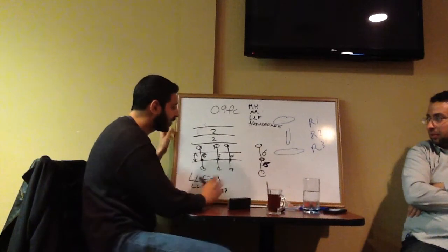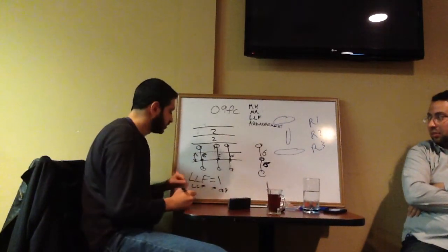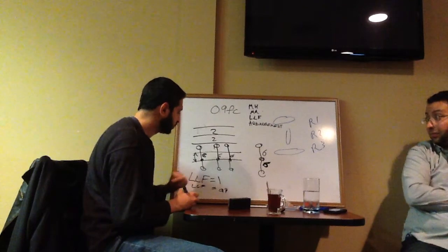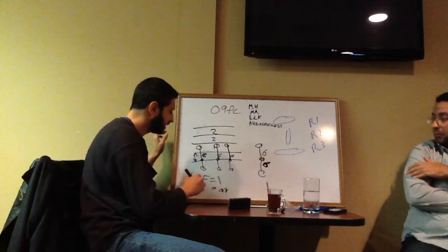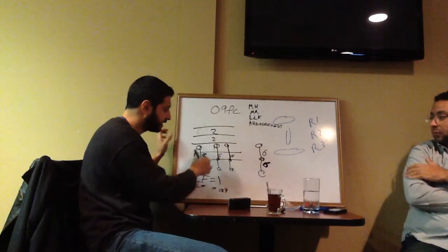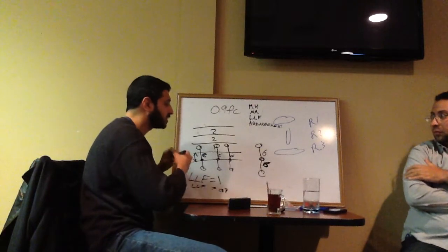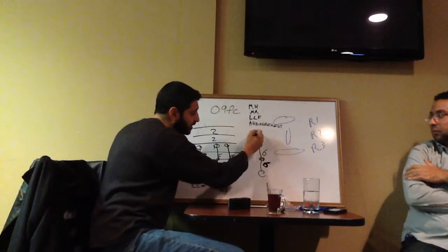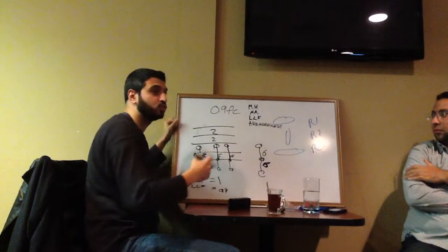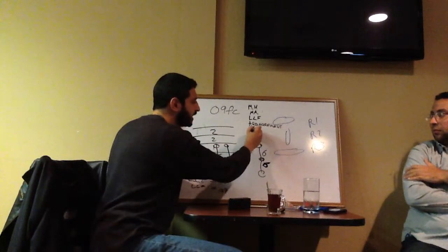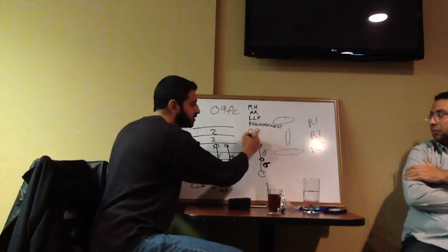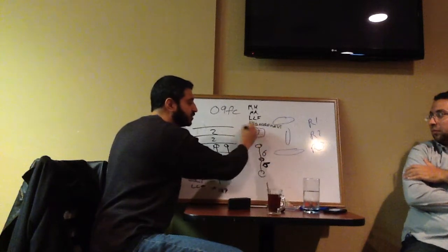Now say I wanted to figure out the spacing in between. I run my calculation with this information and the setback I put in, and you also have to put in what level you want it to be at. Remember that 0.9 we said? We tell it we want a lighting level of 0.9 average.